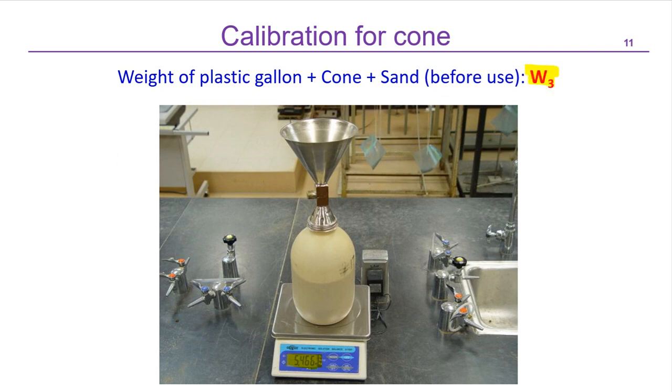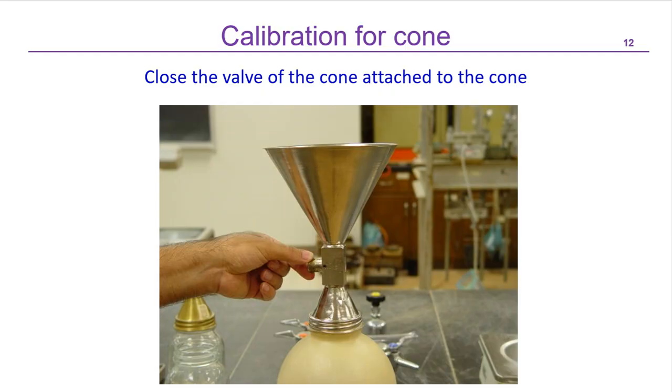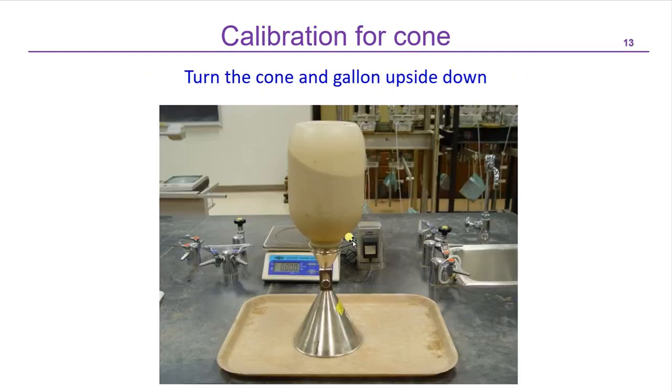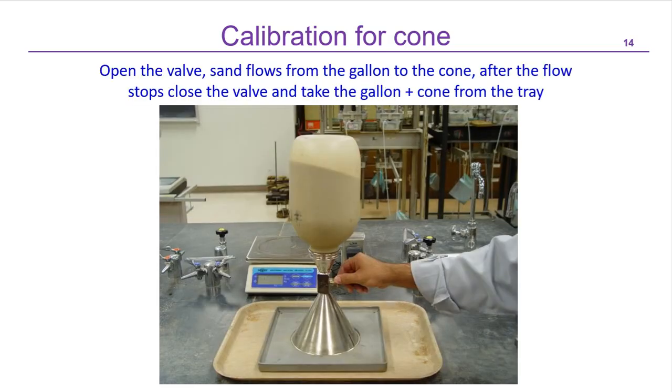Then the next step is to close the valve, and then we are going to place it upside down and open the valve. When the valve is opened, the sand is going to fall down and fill this cone. So sand will fill the cone.